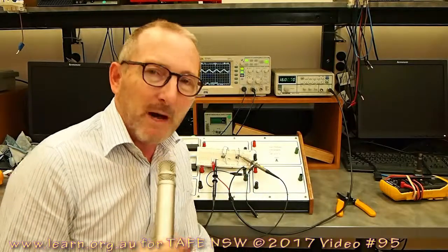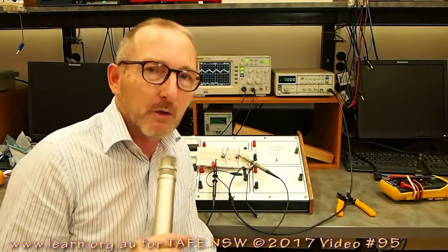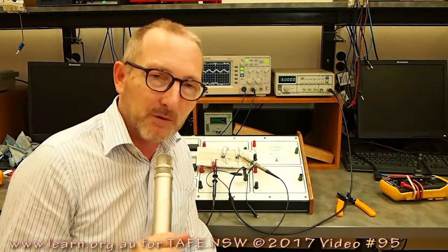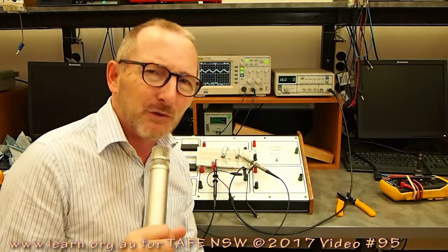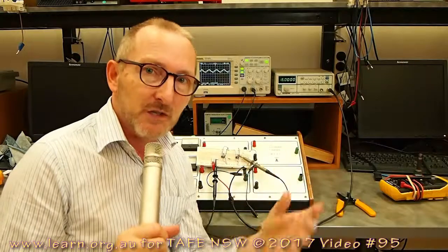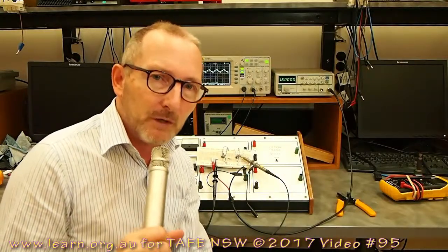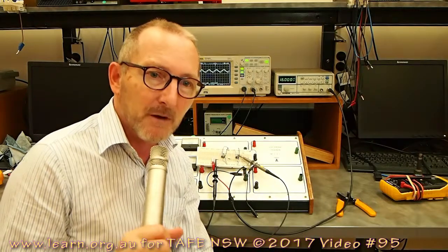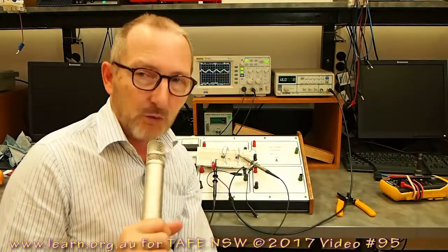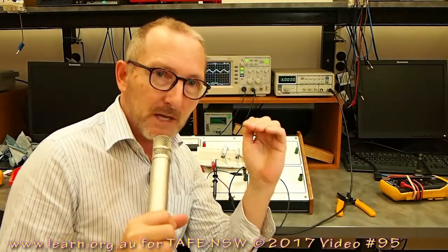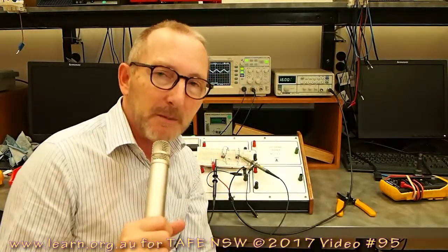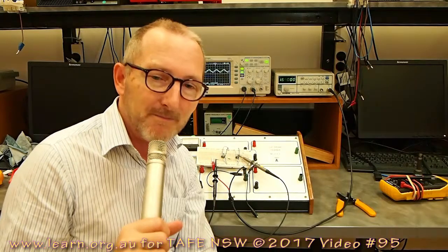So that pretty well wraps up what I wanted to do. We've had a good look at slew rate and frequency and output voltage, and we've seen that if we push our little op amp that little bit too far and we have a big dV/dt, a big change in voltage over the change in time because of the higher frequency at the output of the amplifier, we're going to get quite severe slew rate distortion. And if we don't have slew rate distortion but we push the amplifier too hard, we'll go into the headroom and we'll actually get clipping, which we saw at the beginning of the practical part of the video.